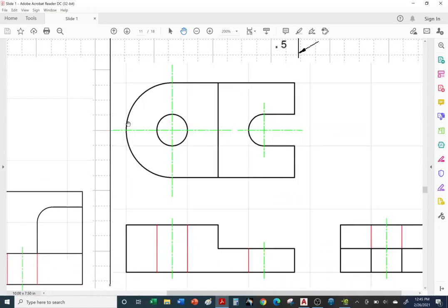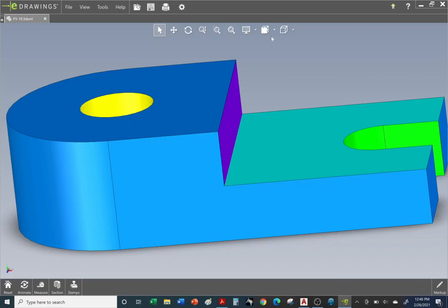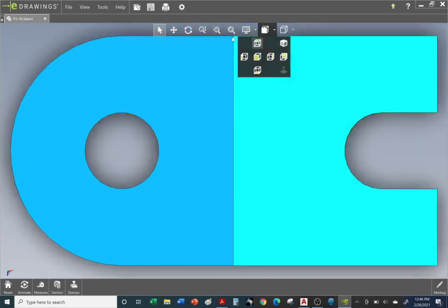Okay, let's go ahead and do the top view. Obviously we have this object line missing. So from this corner, get into the habit of going to all the vertices and projecting, right? And you also project across. It's already there for the right side view, but we are missing this line. Okay, let me show you from the 3D model, top view. So we are missing this object line, and we need our green center lines. All right, so let's go to AutoCAD.